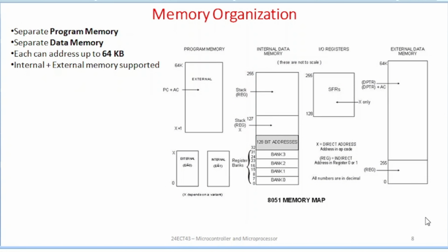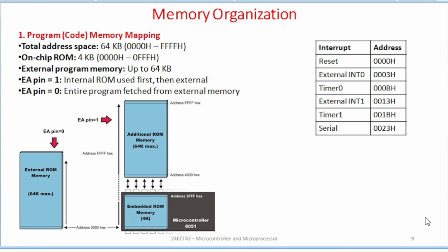In contrast to the program memory, on-chip data memory access needs a single 8-bit value, which is used for a constant or another variable to specify a unique location. Since 8 bits are more than sufficient to address 128 RAM locations, the on-chip RAM address generating register is single byte wide. Different addressing mechanisms are used to access these different memory spaces, and this greatly contributes to microcomputer operating efficiency.